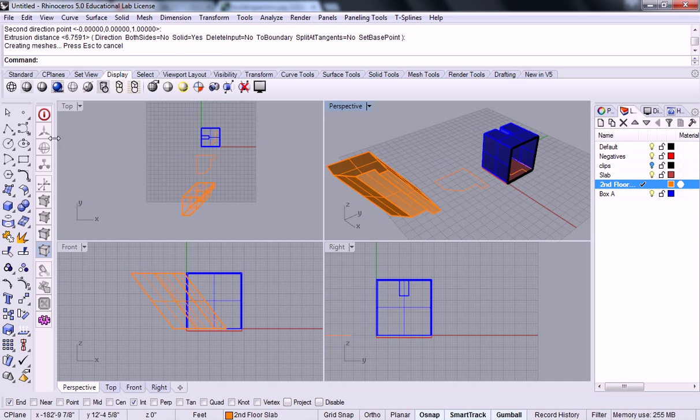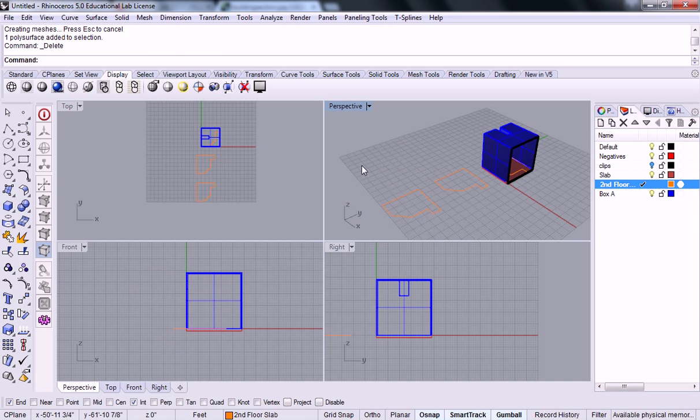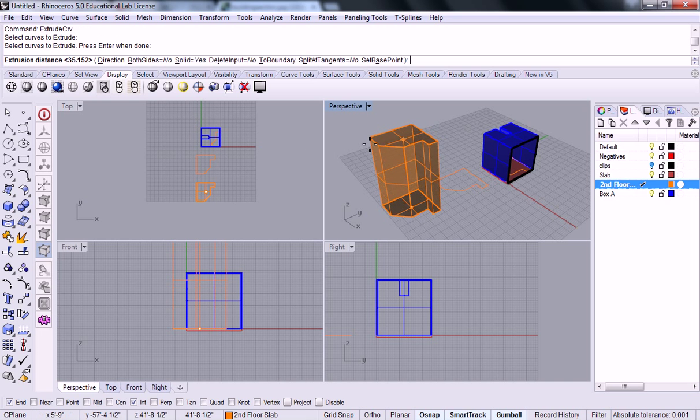No, the points that I chose when I did it, I just did it arbitrary. But I wanted to show you if it accidentally goes the wrong direction, I want you to know why. That's why I'm showing you this. It should automatically, no matter how you have it turned in 3D space, it should automatically borrow the direction. But I overrode it so that you could see what it does. So if I hit enter now, see it goes back to going straight. It borrows the direction of the planar curve that you've created.